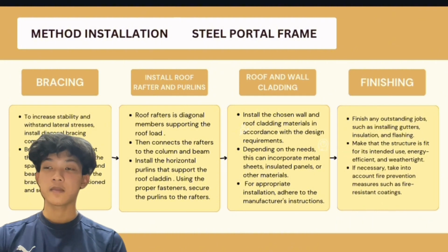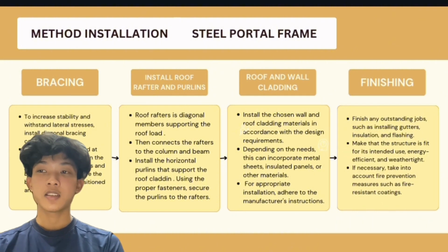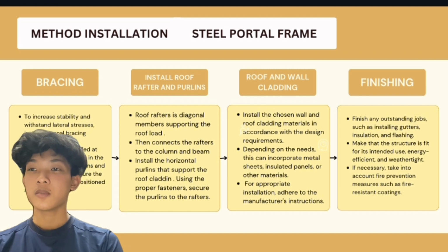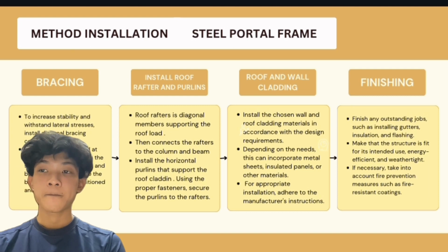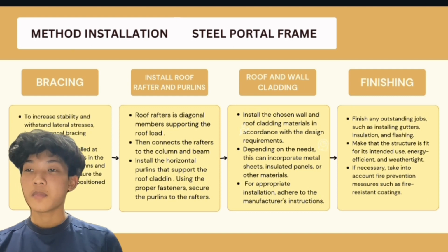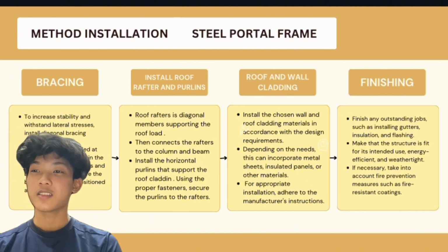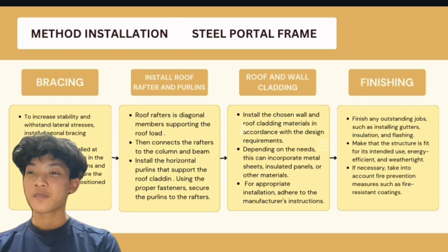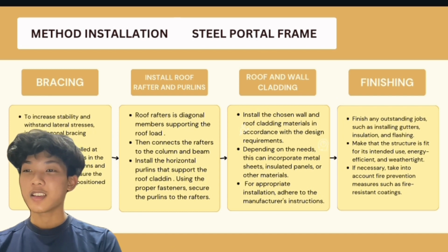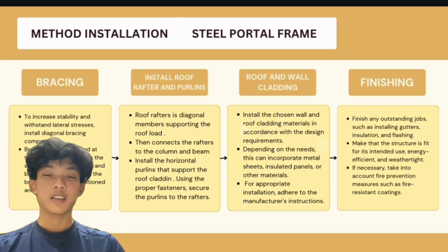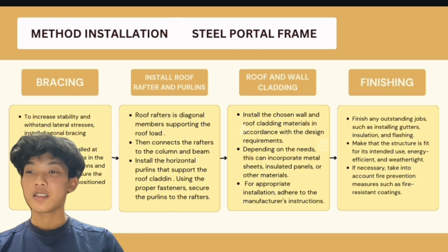And lastly, we do some finishing. Finish any outstanding jobs such as installing gutters, insulation and flashing. Make the structure fit for its intended use, energy efficient and weather tight. If necessary, take into account fire prevention measures such as fire resistant coatings.